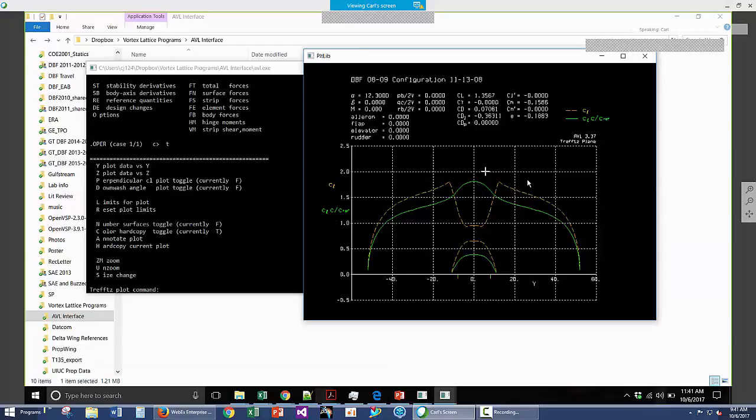But our section CL max was 1.7. Our vehicle CL max is here, like 1.35, a pretty significant reduction. Part of that is the particular geometry that we selected, and we made a compromise by increasing the geometry for the center body, and that's causing some problems. So we can get from our section CL max our vehicle CL max, approximately. This is not an exact result. We're getting a reasonable estimate using information that we already have.